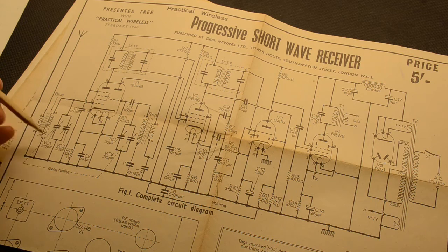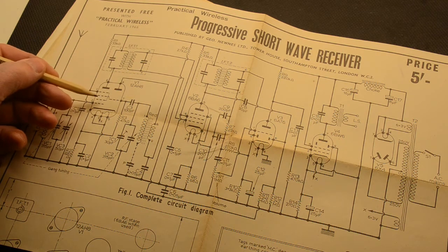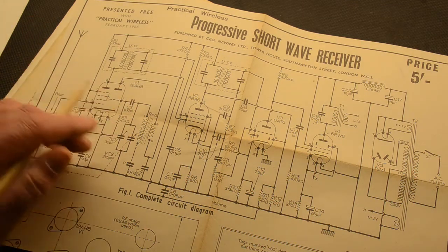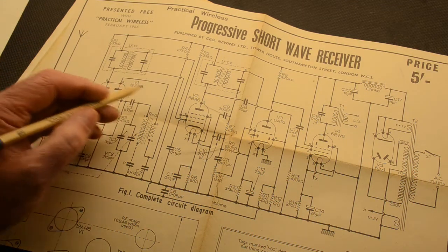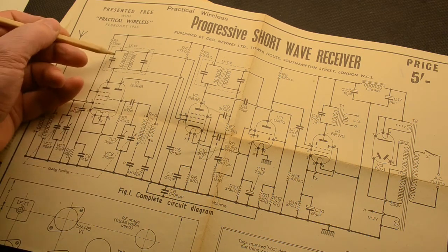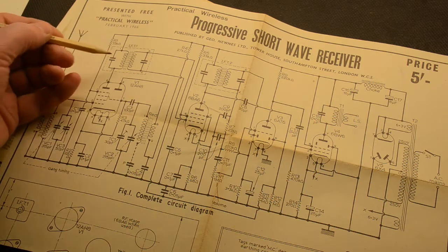What you do is you have the signal coming in here on the left, exactly the same as it was with the ferrite aerial, but of course this isn't a ferrite aerial, this needs a separate aerial itself. That feeds into the control grid in the first valve. Now this half of the valve is oscillating away like our transistor was. It oscillates at a specific frequency to give us a resultant at the IF stage here, which would be 465 kilohertz.